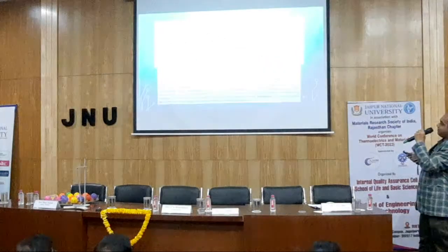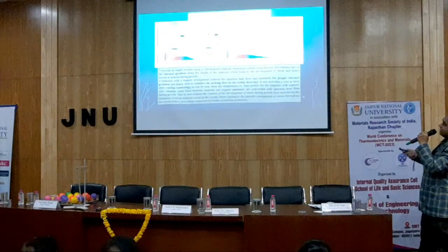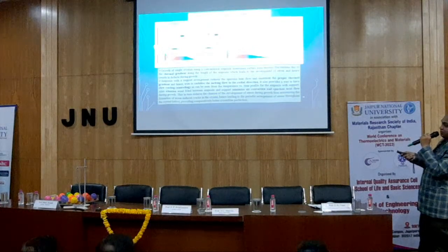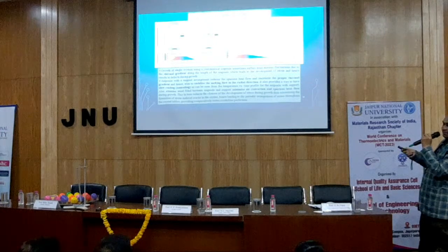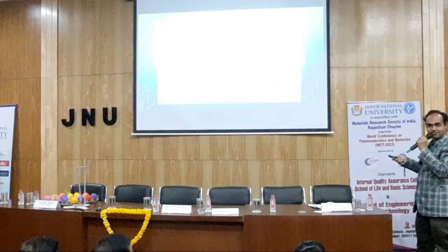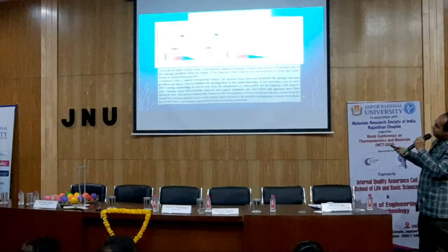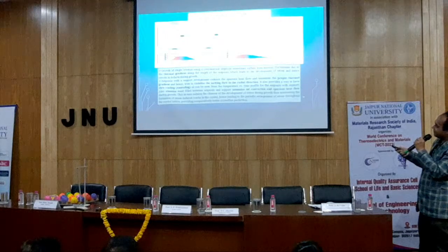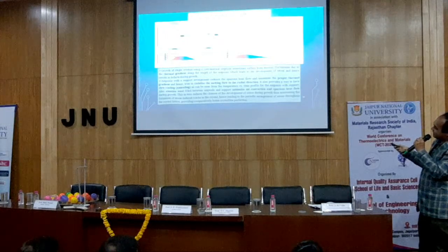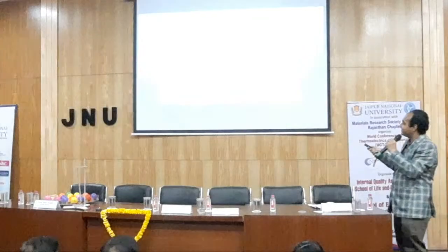If you see, this is the normal method. This is the normal vertical placement method, the conventional one which we follow. But if we do some analysis, either we have to go for high-end techniques or work on the existing design. So we have done a modification in design. We have given an ampule with a support arrangement, and alumina wool is inserted inside. It provides a proper thermal gradient and tries to stabilize the flow of melt in the radial direction.